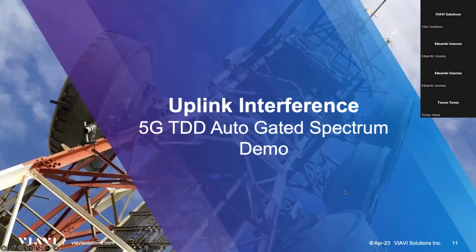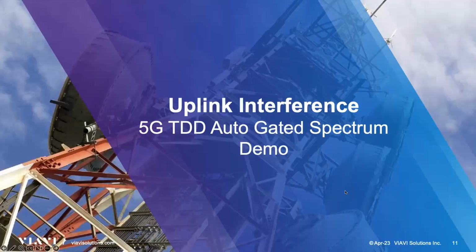So while you're doing that, we had a couple questions come in that we've answered, but Randy just asked one, why we would want to measure the flexible slot versus the uplink slot. It's a great question, Randy. Traditional gated sweep measurements for uplink, absolutely, we're looking at the uplink time slot. The drawback of that is the phones near you, whether they're in your car with you if you're driving, or the customers around you as you're moving, are also using that uplink, and so they will affect the measurement accuracy.